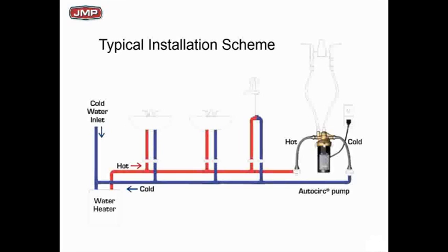If the temperature drops, and there's a little delta T there as well, just say 100 degrees, whatever your set point is, if it senses it, it turns on the circulator, pumps a little bit of hot water into the cold water supply side until that temperature is back up to set point, whatever you got set. It's very little water, cuts right back off. It's not going to upset you because it's just a touch of hot water to the cold water side to maintain it. So when you go to that fixture to take a shower or wash your hands, you got hot water instantly.